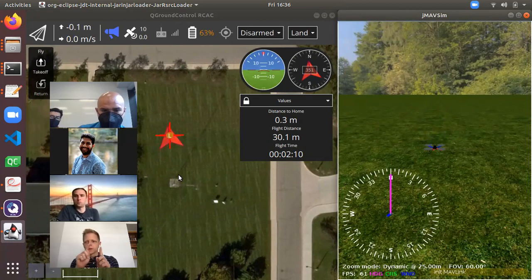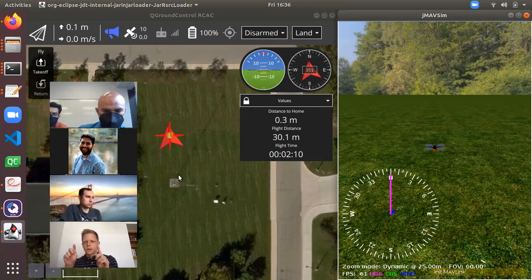So at each time, we're stringing a bunch of points in the trajectory, and we're sampling those slower, right? So as we're going along, effectively what we're doing is limiting the response that you could get from the velocity control. If we just issued one point that was a long way from where we are, then it would rely on that velocity controller to reach max speed, take us to where we are, and then stop.